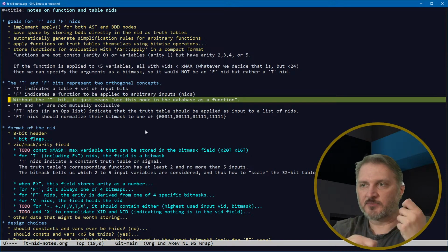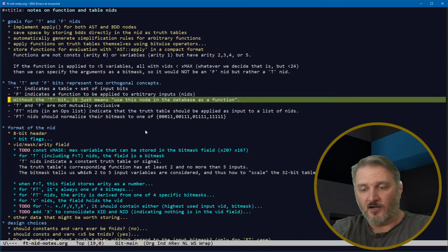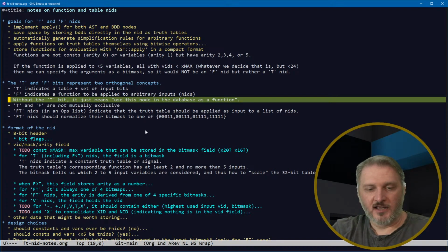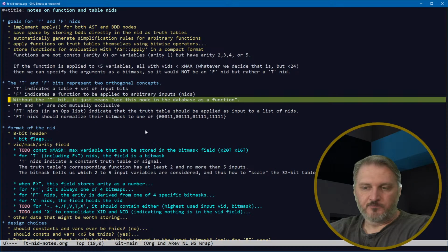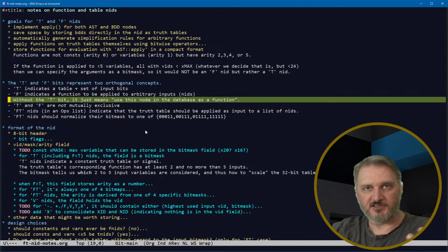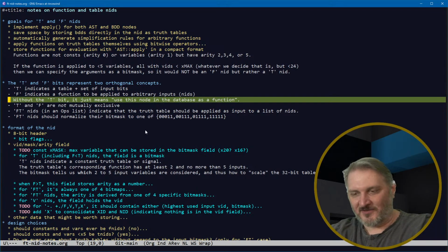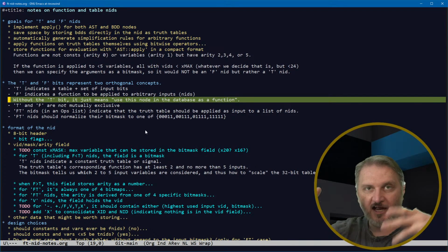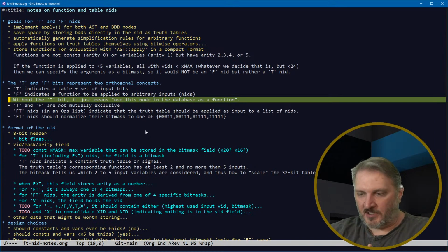And so if you do a bunch of additions of 32-bit registers, then maybe you can find some way to optimize those functions, and you get the benefit of optimizing them everywhere you do the addition, rather than having one gigantic sprawling thing where every single time you do an addition, you have to redefine it in terms of AND, OR, and XOR and all those things. So now you can have these higher arity functions, where you have multiple inputs and they're more complicated functions.